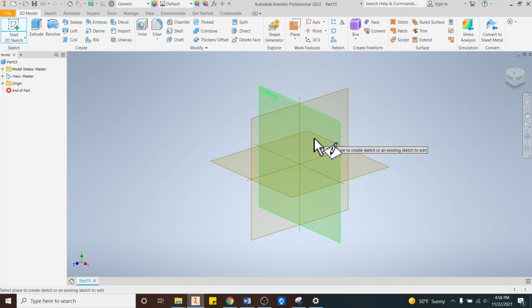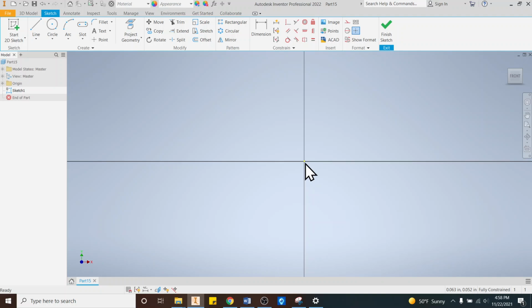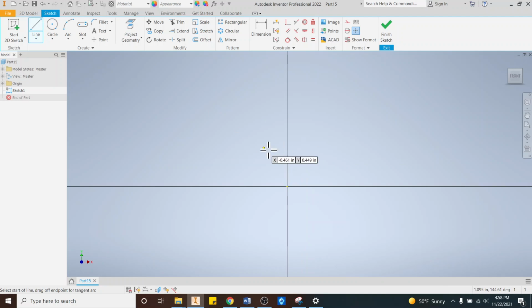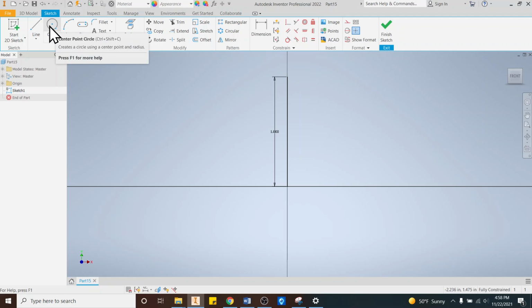When I start a sketch that I know I'm going to revolve, I keep it simple. First I'm going to do the donut, and I'm going to show you two ways we can revolve it. We want to revolve it about one of the axes, and I'm going to generally use the y-axis for this. So I've got my line tool. I'm going to draw a line right here, make it an inch. The length actually is not super critical, just kind of right there. We're only going to use it as a reference point.